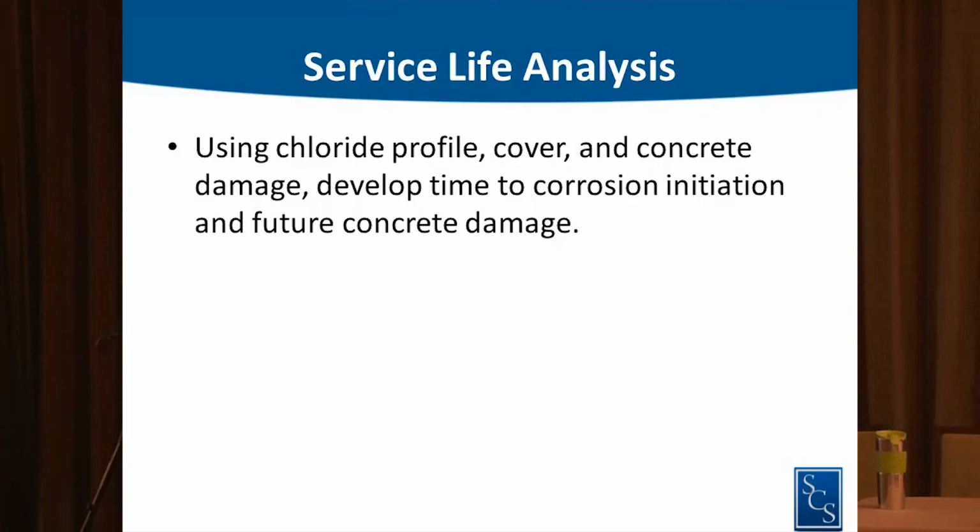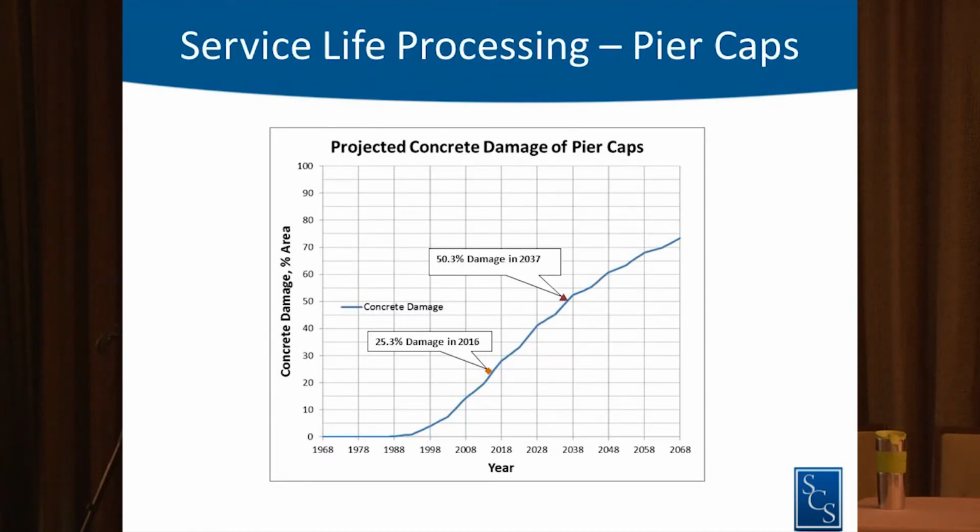So you would expect a higher damage, right, in a shorter period of time. And so if you look at this information, you do a service life analysis and project your future deterioration. As you can see in the cap, it's already 25%. If you don't do anything, it's going to double in about 20 years. And at that point, your options are very limited, right? Any repair you do is going to be expensive, or you're going to have to replace it.